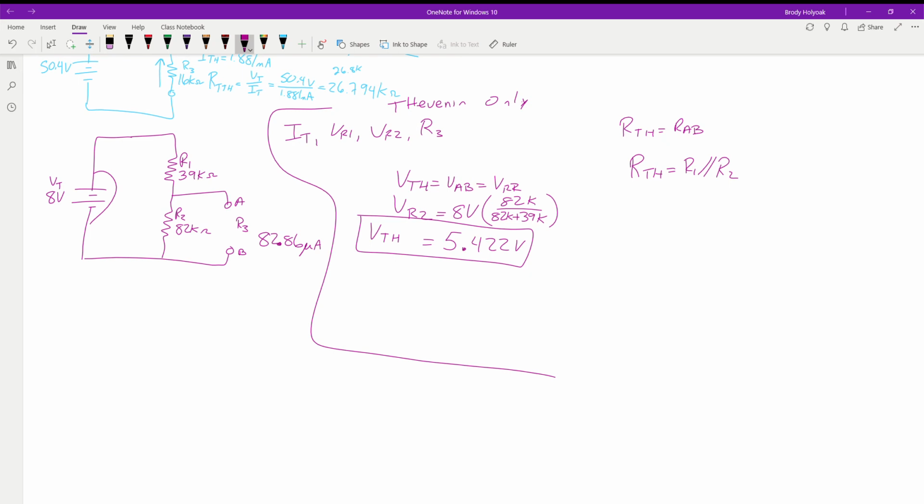When we solve this, we're going to get a value that's going to be around 30K ohms. It's going to be less than the 30, but as this gets farther and farther away from it, we're going to start approaching our smallest value. That's why, when we use our voltmeter, it has 10 megs of resistance. If we put it in parallel with a 1K, we still have about 1K. So we get 82 in parallel with 39.